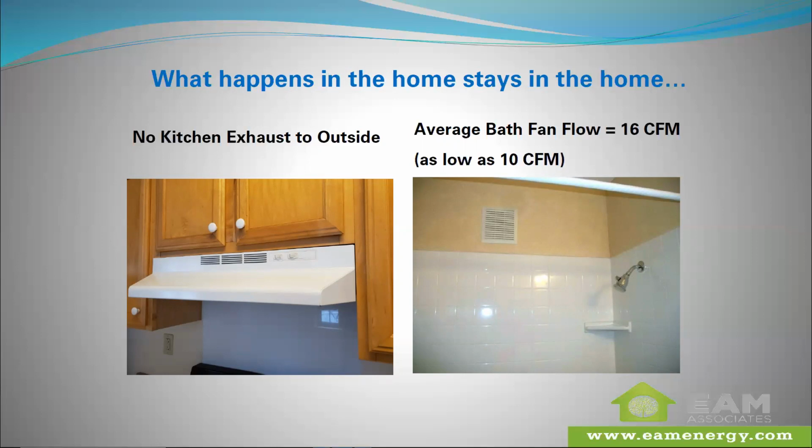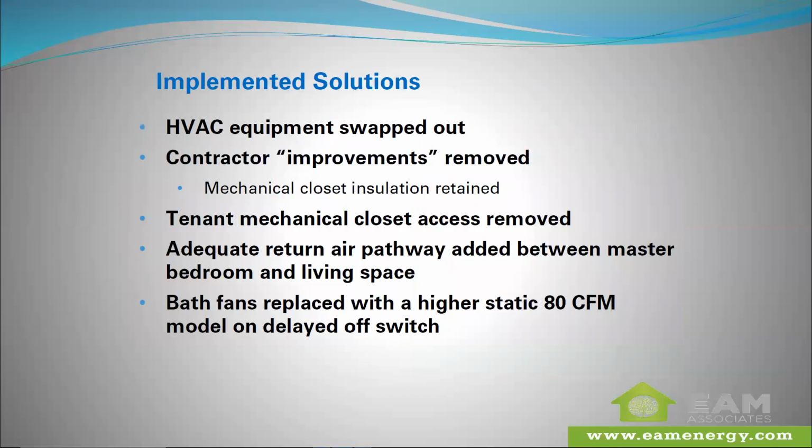Once it starts to settle and condense on all kinds of surfaces, you're already kind of losing the battle anyway. So that was one of the reasons why the clothing in the master bedroom was horrifically moldy. There was a lot of moisture during the shower events that was not able to get out properly. And due to the extreme negative pressure being created in the master bedroom, the closet existed in between the bedroom and the bathroom. We had moisture getting sucked right through that wall and soaking those clothes in that dark closet, and the mold growth was activated.